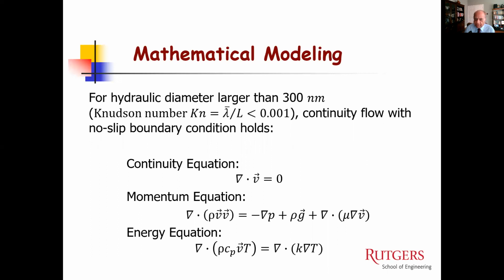So many of those things come in, but if it were air or nitrogen, we would be dealing with slip at the wall, and we'd be dealing with the temperature jump. But with the liquid, which we are considering here, that's not the case. It's a much simpler solution with respect to the heat and mass transfer in the flow.